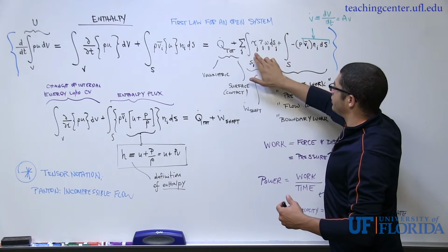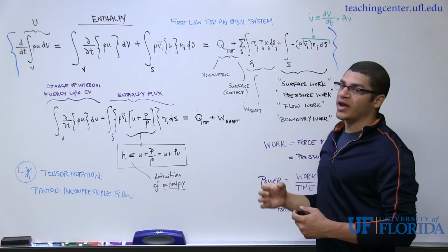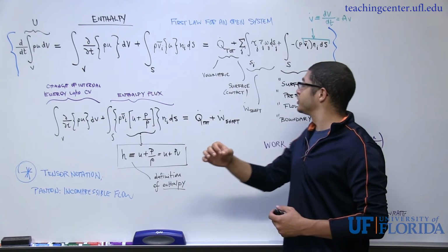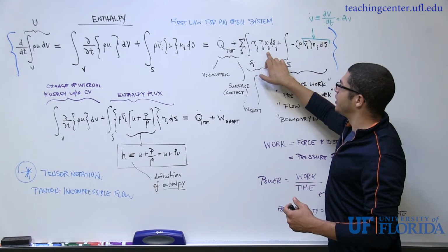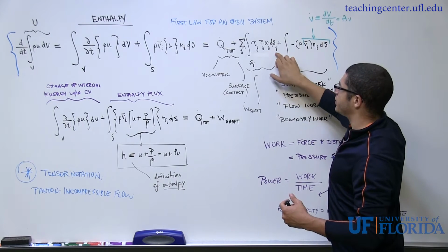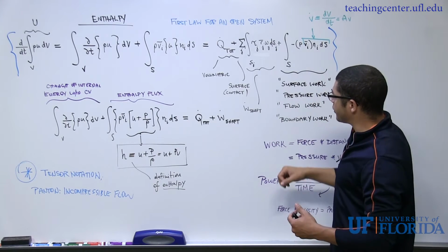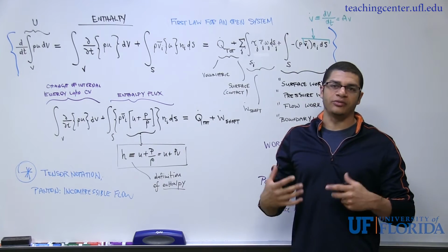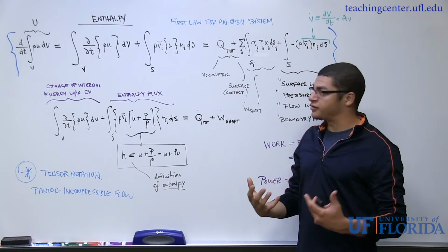And I want to take the product of that shear stress and then also the radial distance from the center of the shaft to where that stress is acting, and then also the angular velocity of the shaft itself. And so the product of these three with the differential cross-sectional area element. Actually, just to take a small side note, because I think it's better if we look at the units to make sure that we're dimensionally consistent.